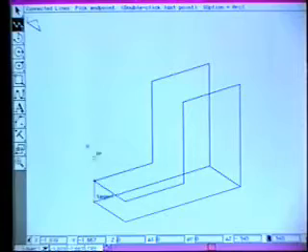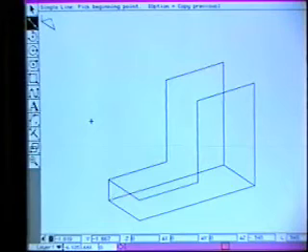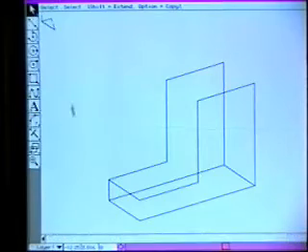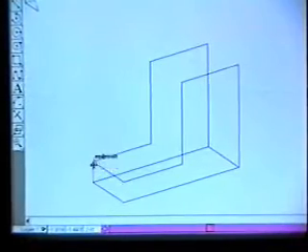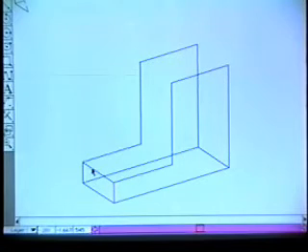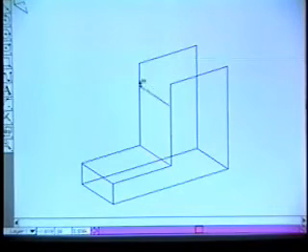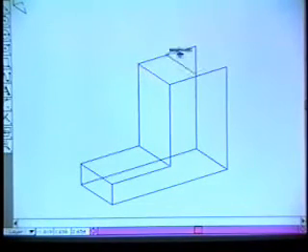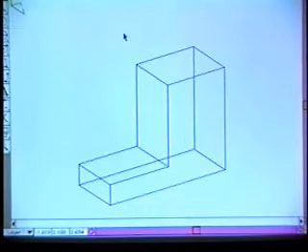And then I'm going to change tools. I'm going to go and get the single line tool. And actually I don't even need to do that. Every line is available for me there. If I pick the selection arrow, I can take this line, and then I'm going to hold the option key, because option equals copy, and I can grab this and move a copy to there. And then I can pick this line and move a copy with the option key to there, and move another copy to there, and a third one to there. So now I've finished a rough outline of an L-shaped bar, and that would be the initial layout of my design.